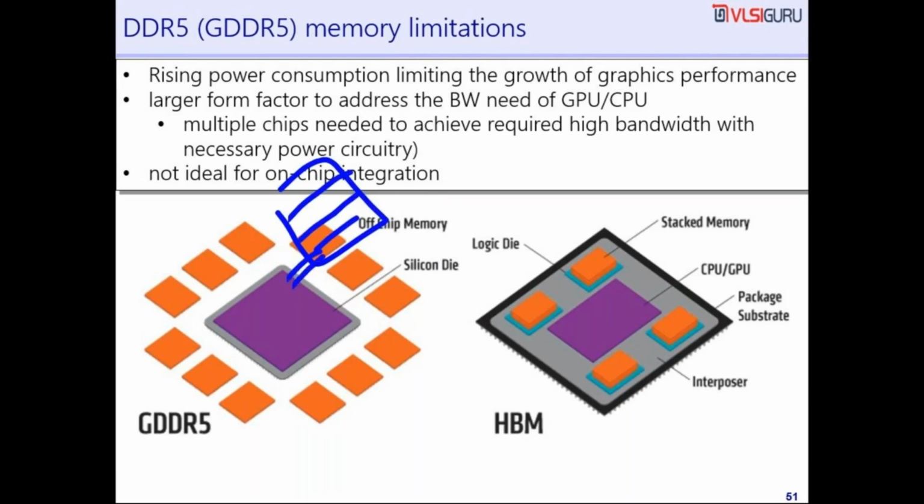And you may still have one or two channels only. You can select which rank you want to access, so you still have the capacity advantage here. Whereas here the problem is you are only relying on the 3D stacking. Now there is a limitation on how much stacking you can do, 8 or 16 maximum. You are also limited by the amount of area and the number of pins, all that essentially ends up limiting the memory capacity here.